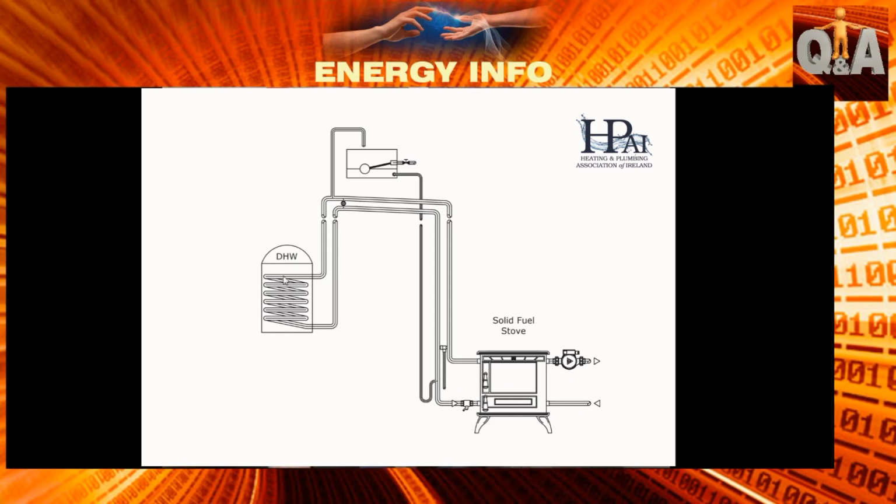How open should the valve be at the top there to allow the air to go through? Just enough to let the air pass, but I would not have it so closed that it might ever obstruct, because obviously it's a critical pipe not to have air in. I would have it open, and maybe let's say there was 10 turns, I might have it open 1.5 or 2 turns. So just cracked open. Beyond cracked open. Yeah.